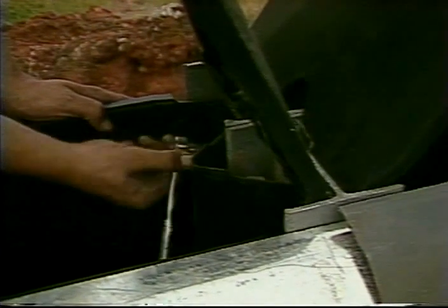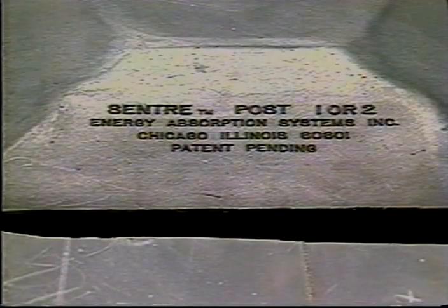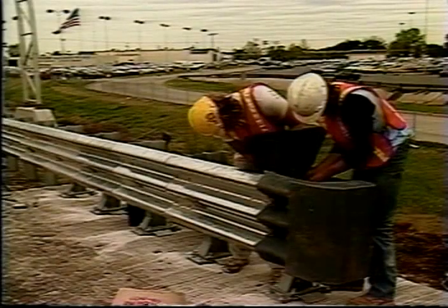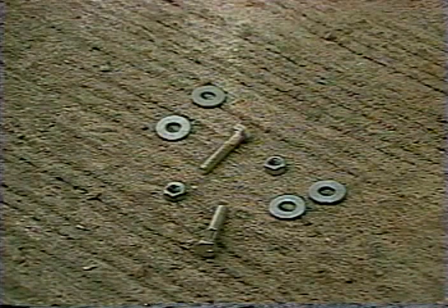Next comes sandbox placement. The sand containers are attached to posts 1, 2, and 3 and are labeled with their proper post numbers. Place the correct container on each side of these first 3 posts. Use 2 bolts, 4 washers, and 2 nuts to attach the containers, sandwiching the post and blockout between the containers. Fill the containers with clean, dry sand to the top edges and snap the lids closed.